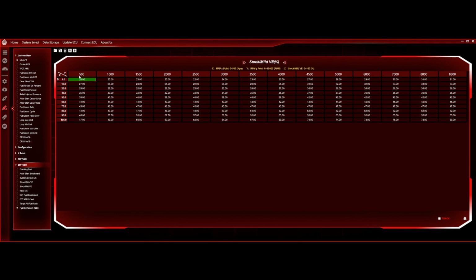So you need less fuel. We're not going to be burning at exactly stoichiometric, but for the purpose of this, say you wanted every cell to always be burning at stoichiometric, the quote unquote perfect complete burn of fuel for your engine, right? So this will dictate what your injectors are doing.